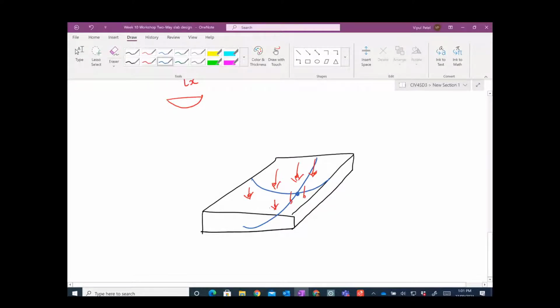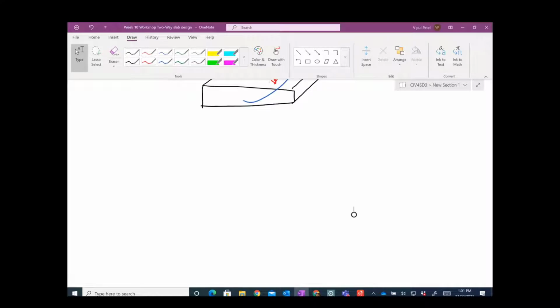Now you remember the first thing that we might need to assume. Look, when you have two-way slabs and one-way slabs, the two-way slabs are stiffer and stronger, and therefore you need a thinner slab. So generally in practice, engineers prefer two-way slabs. So two-way slabs can be thinner. If you use one-way slabs, they would have a greater thickness. If you remember, last time we had some thick slabs that we used, but in the two-way slab, typically this is a general rule of thumb.